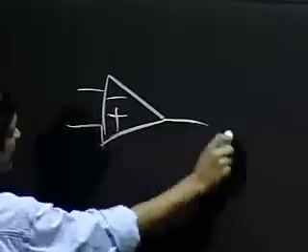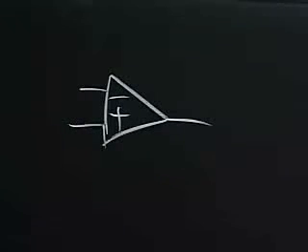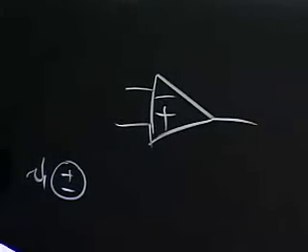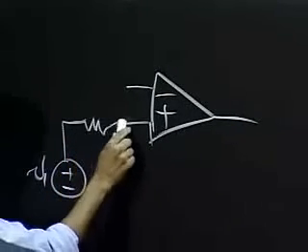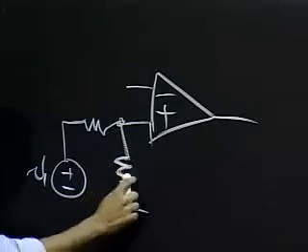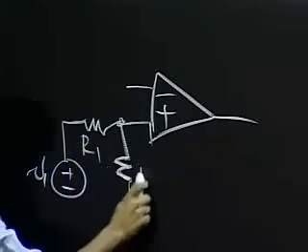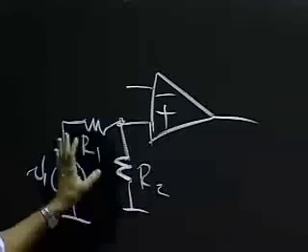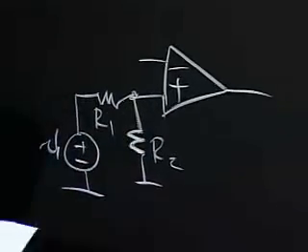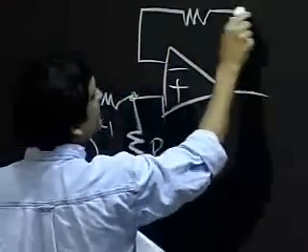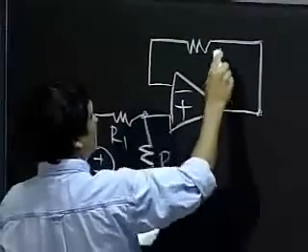So with op-amps, I start with this little guy. And what I'm going to do is use two voltage sources, V1, and this is a resistor, not an inductor, and value R1, value R2. So I have a voltage connected by a voltage divider to the plus input, and I'm going to provide some negative feedback in the following way.